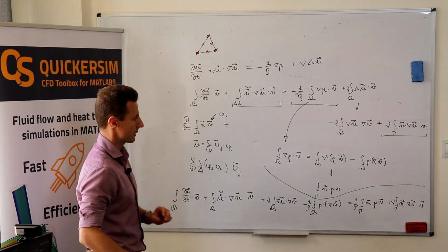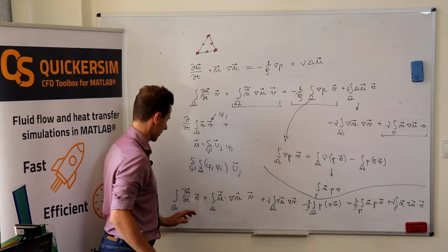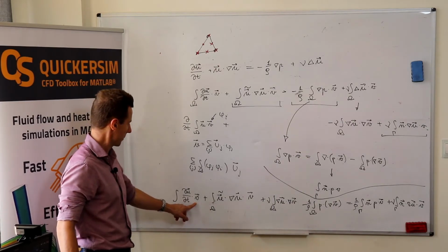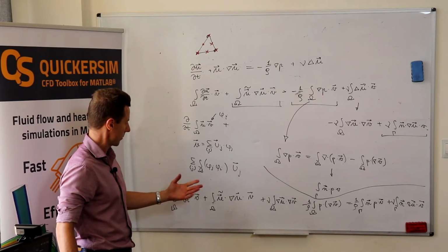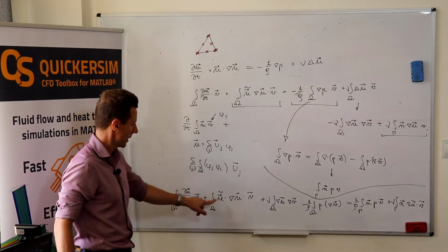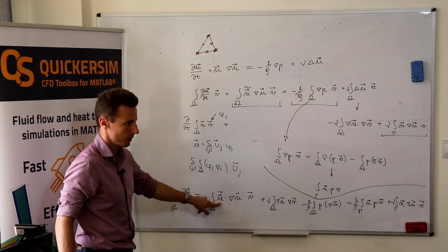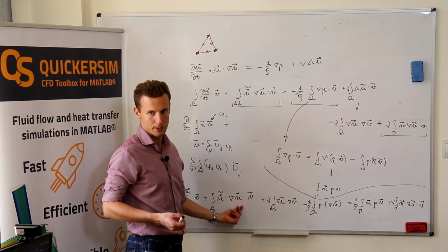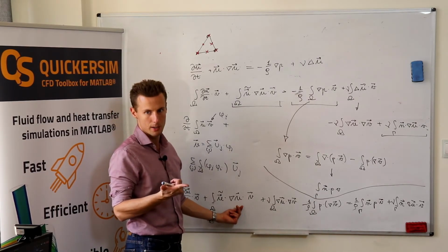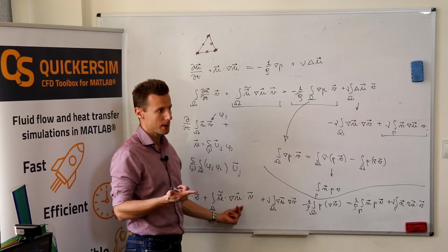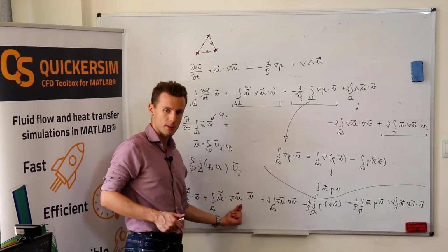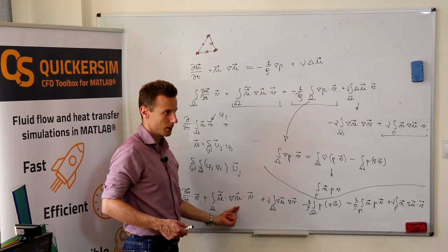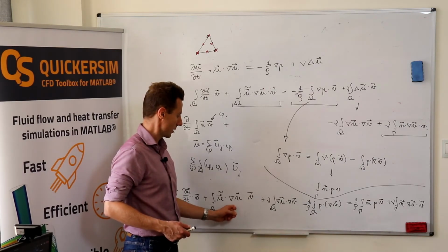Okay, if it's fine, then let's have a short discussion. Test functions, we can calculate them. This one will be transformed to the sum of the shape functions times the unknown coefficients. We do some approximation of the convective velocity. Here we will have the gradient of u, but u will be replaced by shape functions times unknown coefficients. Gradient of shape functions can be computed. We did it for the diffusion problem. Right now it will be easier.